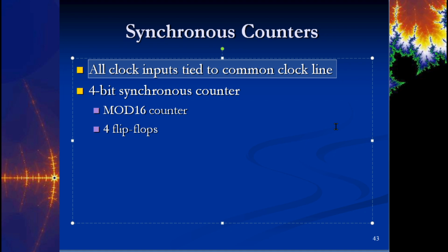It keeps summing together. So if you have 15 flip-flops in series, or if you have them cascading into one another, that's 15 propagation delays. And let's say it's 10 nanoseconds. That's 150 microseconds that you have to deal with. I'm sorry, nanoseconds, right? So that could potentially miss a count depending on how quick your frequency is. So the difference is now you only have one propagation delay, and so you can run a much faster circuit with just having that one single propagation delay, and you don't have to worry about how many of them you have cascaded together.